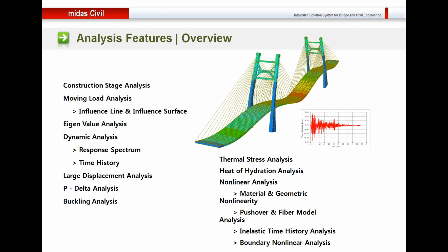And we have a separate set of advanced analysis features in Midas Civil. So you can perform thermal stress analysis, heat of hydration analysis, nonlinear analysis in terms of material or geometric nonlinearity, and you can also perform pushover and fiber model analysis. So basically, all types of analysis that you might need for obtaining results on the bridge structure that you might design are available in Midas Civil.